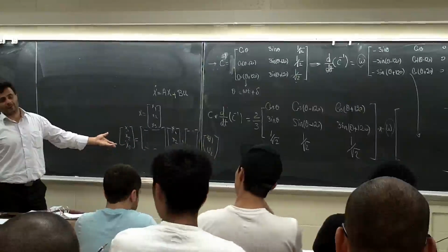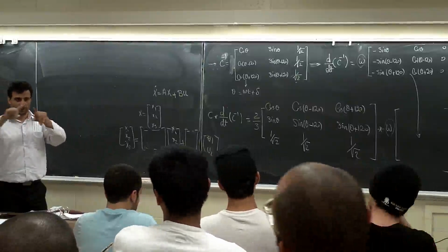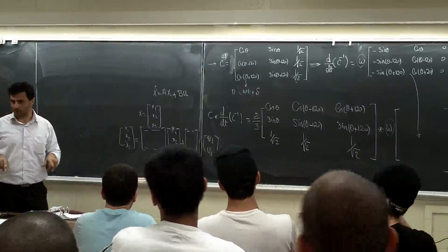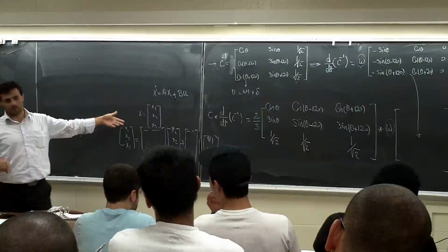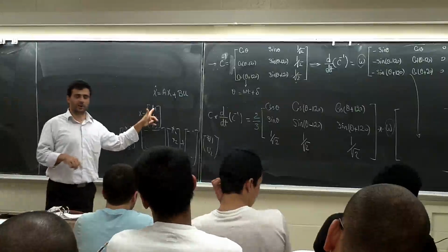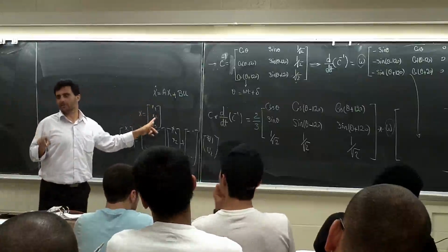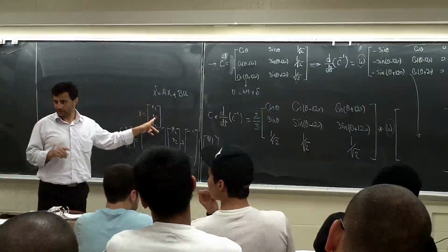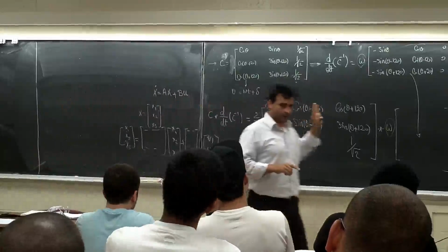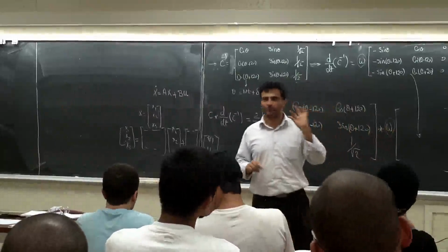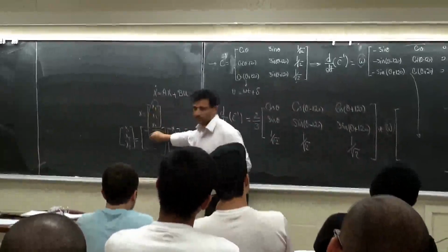When you have capacitors and inductors, have you ever written the matrix form of the equations for them? This is the same. This is a capacitor. For every inductor, I is the x, and for a capacitor, v is the x, because they call them state variables. The current of the inductor and the voltage of the capacitor are state variables.